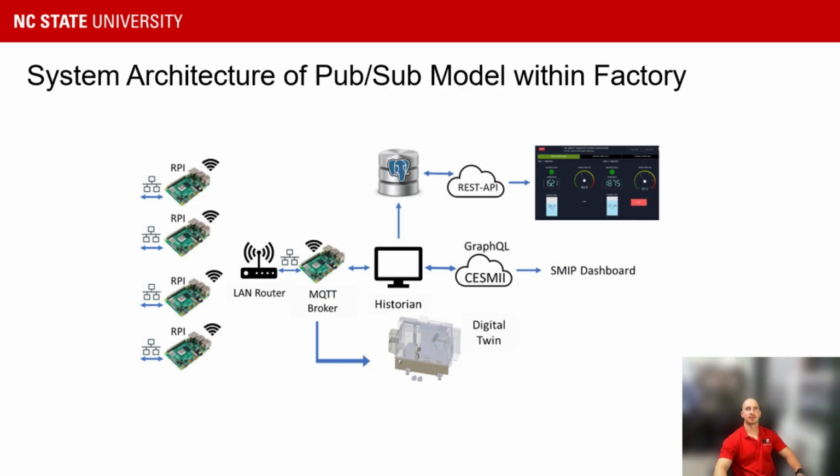Various machine assets on the shop floor can publish data to an MQTT broker via the topic hierarchy specified by the Sparkplug B specification. Different subscriber nodes listen to specific topic namespaces, pick up the messages, and process them as needed. The subscriber nodes themselves are not directly communicating with publisher nodes. The communication happens only through the MQTT broker topic channels. If industry standards are available, such as MTConnect for CNC machines, you can structure the data sent by the publisher.